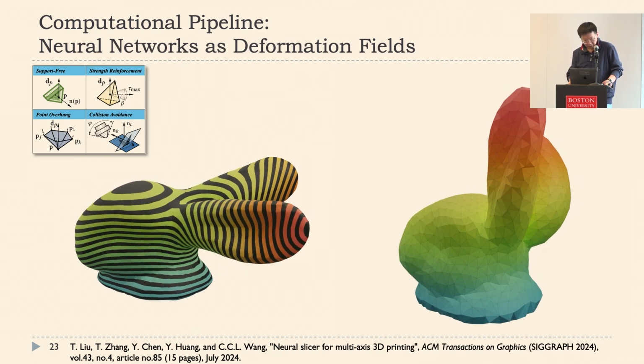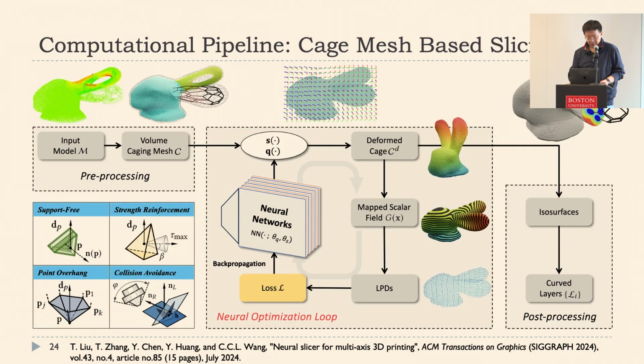That's pretty good. And then we're able to conduct everything in the cage instead of on the original mesh. The good thing is that our original models are already converted back into a solid-based representation. With the help of that, we're able to generate those layers inside the cage and use the implicit solid to conduct a Boolean operation to get a clean boundary for those layers.